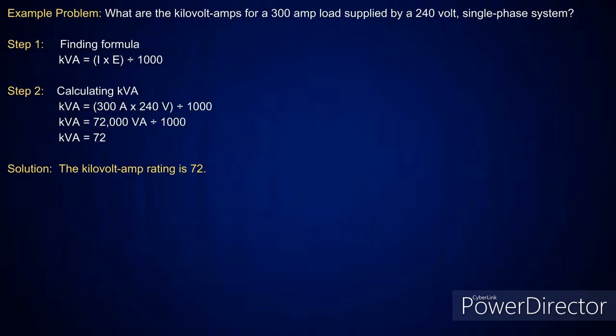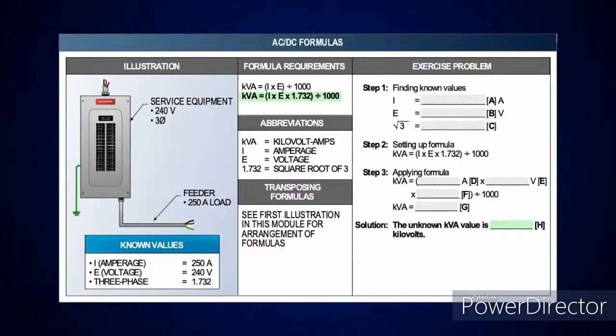One thing I want to bring up, James, and you kind of taught me this when we first started going through this, about when we did the 100 foot rule about the 1,000 foot multiplier. I really enjoyed that. So everyone knows, when we first started talking about this, James had a rule of thumb saying if you have to go over 100 foot, then you have to include voltage drop, because when they first made the ampacity table, it's based on 1,000 foot. It was burning conductors up. They realized they had a mistake.